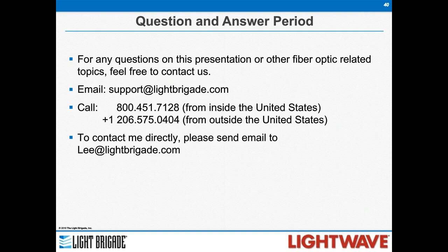If you don't have a problem in that cassette, then using an OTDR to test through that, it will show a loss. It will be a combination of whether it's a splice or two connectors in that cassette. It will show that as a loss. So if you're in spec, then it's no problem to use the OTDR to test that. If that is reported as out of spec and that's where your cassette is, then to really troubleshoot it, you're probably going to go in with a visual fault locator through one of those connectors and try to see where the problem is. So you can use it. It's just not going to give you a precise location within that, if it's a splice or if it's two connectors, which connector it is, because they're just too close together.